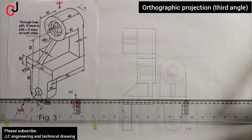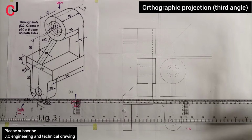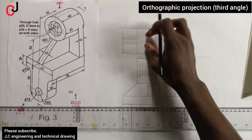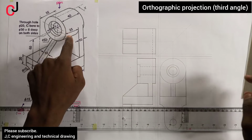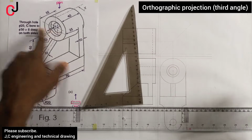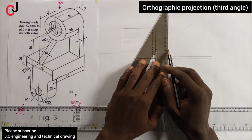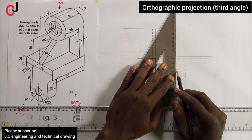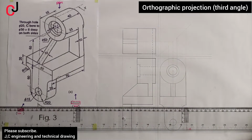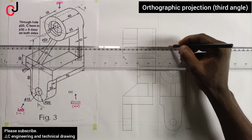And also, from this, you can see while looking at it, this is the circle, this is this circle here. So you can see the 20, this is the 20 through hole. So you project your 20 mm upward. Once it hits at 45°, you project to the left.